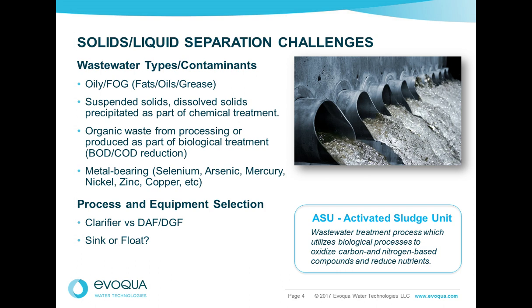And I'm not sure whether we're going to be able to satisfactorily answer these, at least in the specific sense. There are just many unique, often process-specific challenges for each application to be considered. Density of the solids to be removed, variability of flow and composition, and the fate of the solids to be removed, and of course, ultimately, the treated effluent quality guidelines.